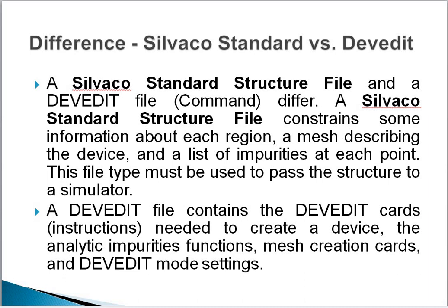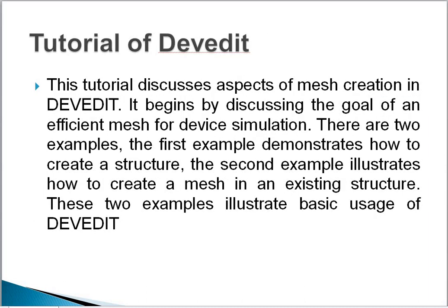A DevEdit file contains the DevEdit cards needed to create the device, the analytical impurity functions, mesh creation cards, and DevEdit mode settings. Tutorial of DevEdit. This tutorial discusses aspects of mesh creation in DevEdit. It begins by discussing the goal of an efficient mesh for device simulation.